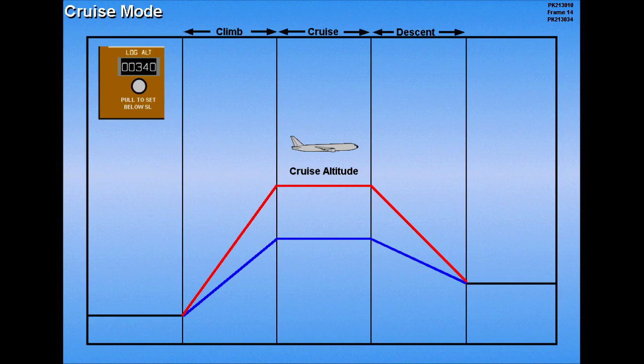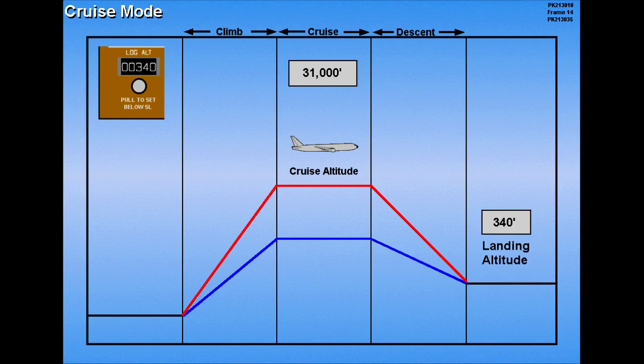If the aircraft altitude remains constant for 1 minute, the cabin enters the cruise mode. At that time, the cabin controller compares the selected landing altitude with the scheduled cabin altitude, and then selects the highest for the actual cabin altitude.